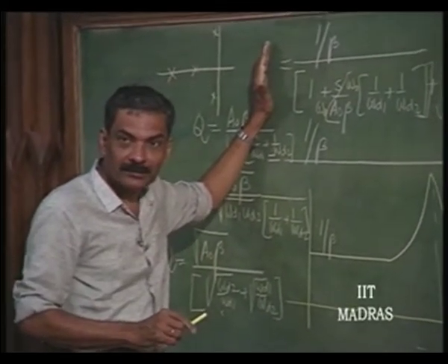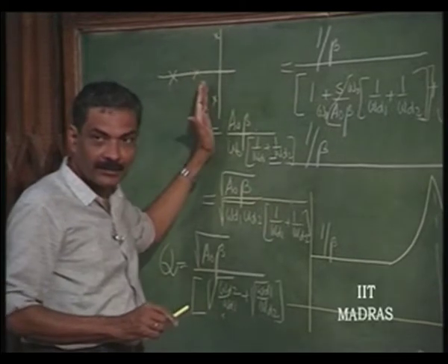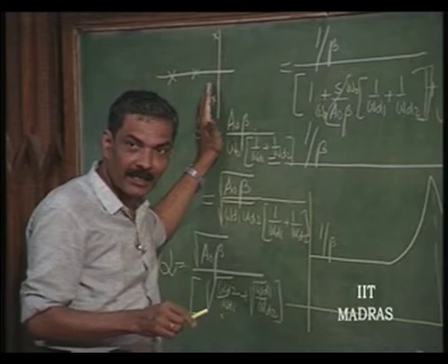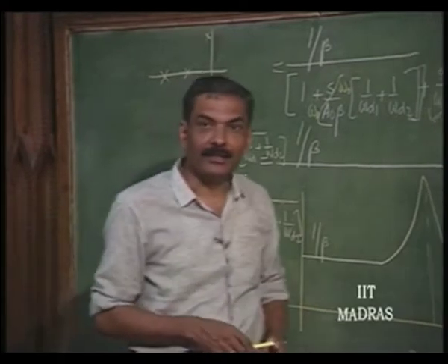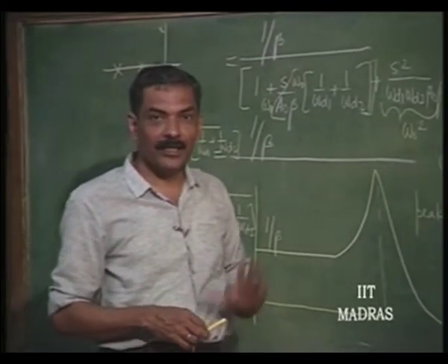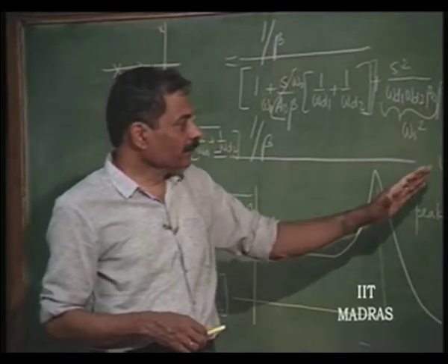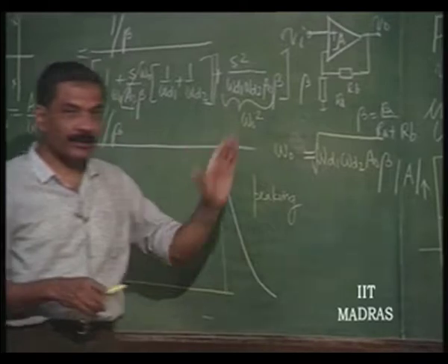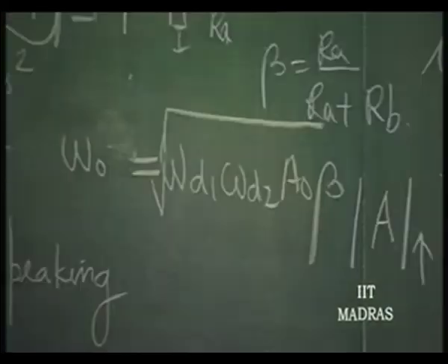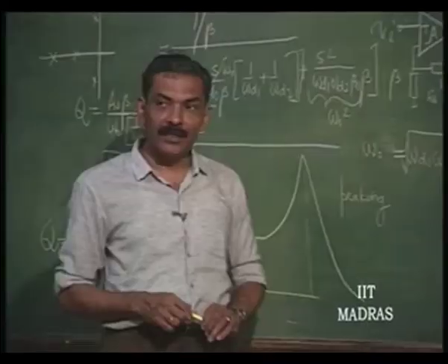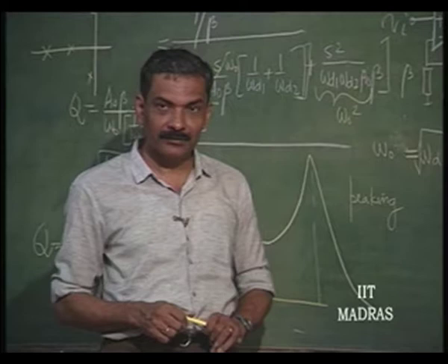If it can lie on the imaginary axis, if it is a third order system and the loop gain is high, it will definitely oscillate, and the poles will definitely lie on the imaginary axis or on the right half of the s plane. So, it will go into oscillation. So, this is the frequency instability in negative feedback amplifiers.